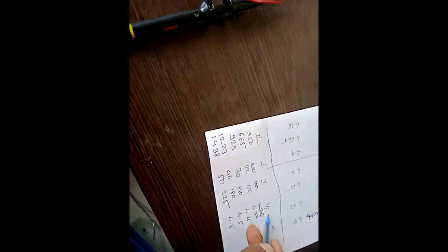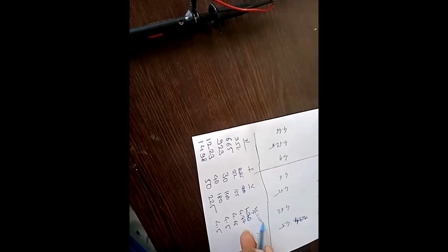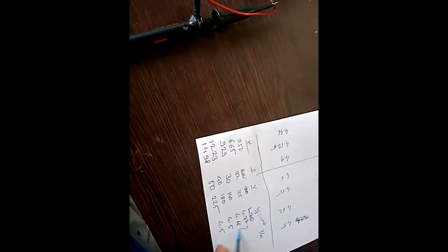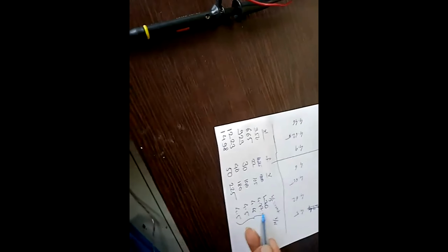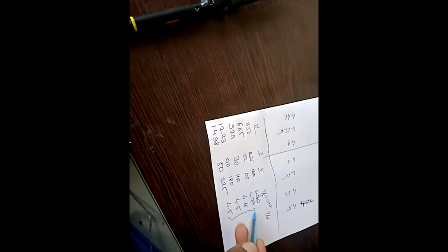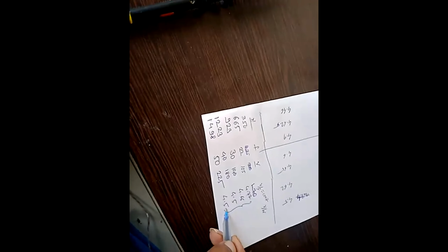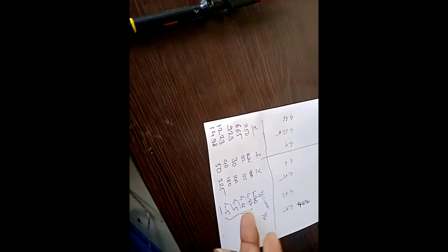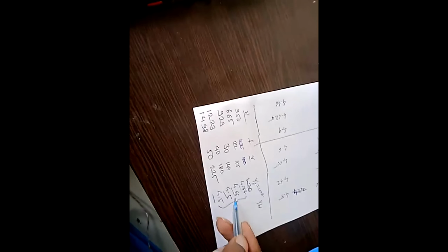It means V by F is equal to constant. So 4.7, 4.6, 4.5 are the constant values. Whatever we change in voltage and frequency, we get constant torque and the speed will increase. Clear? So all values should be almost the same, approximately 4.5, 4.6.